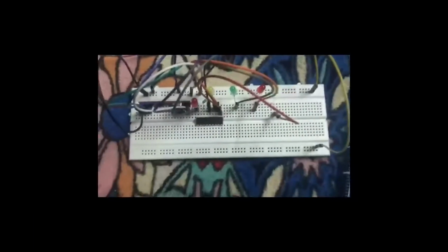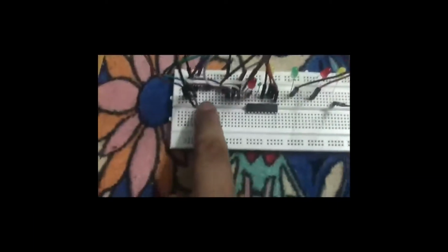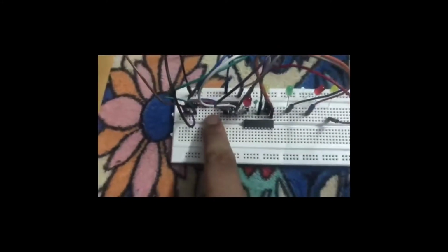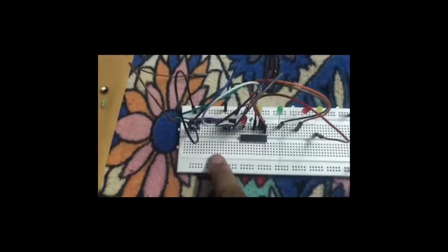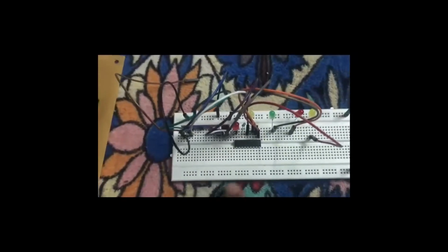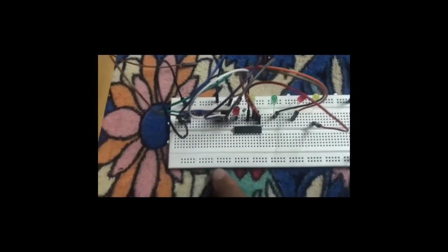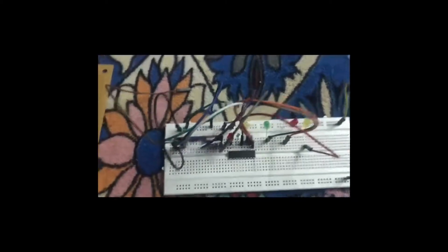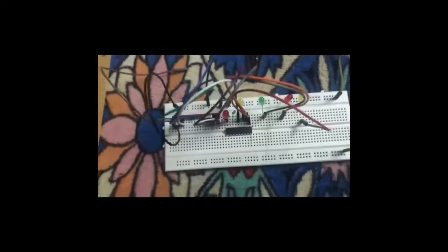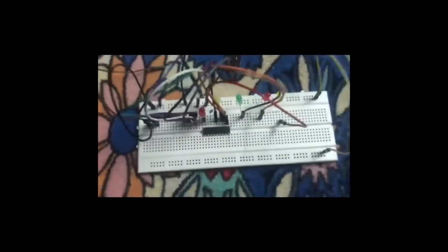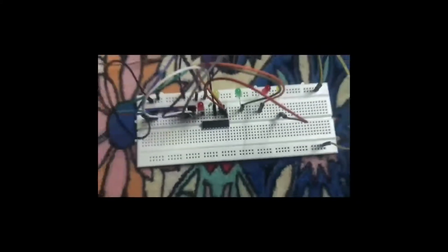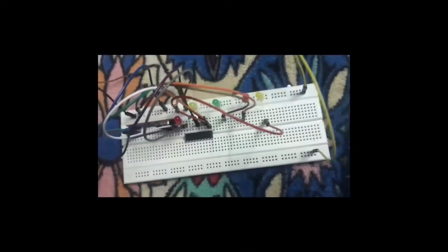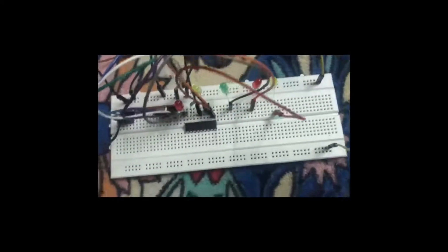section of our project. The signal is received by the RF receiver, which is right over here. The receiver module has 4 pins, namely VCC, D out, linear out and ground. VCC is powered by a 5-volt supply, and the operating current here is less than 5.5 milliampere. The pins D out and linear out are shorted together to receive the 433 MHz signal from the air. The signal is then demodulated and sent through the data pin.